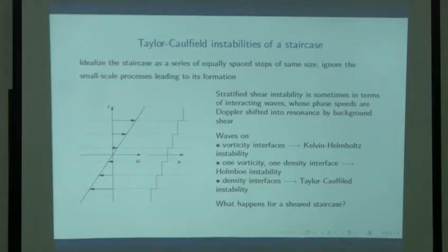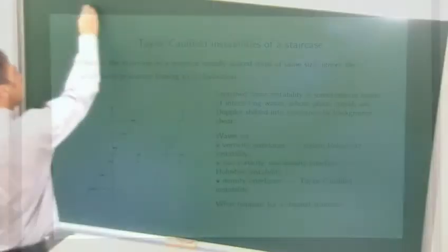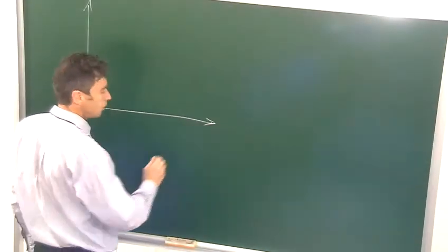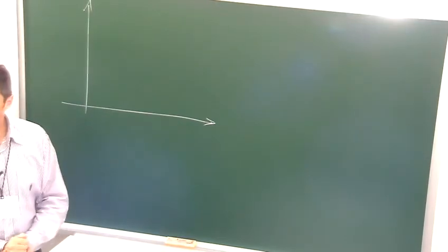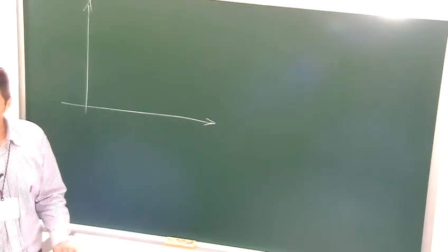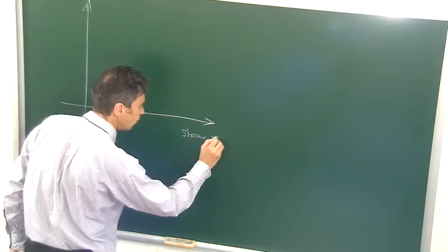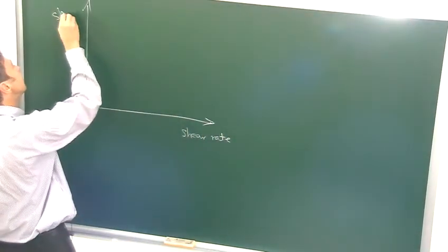So, rheometry. In rheometry, when you have a complicated fluid, you have something like two plates. You spin the top plate, or you have a plate and a cone. You put the fluid between these things. You measure, for example, the torque as a function of the rotation rate. And that allows you to build up a cartoon of the material behavior of non-Newtonian fluids. And the cartoon is usually portrayed as this picture where you have shear rate against shear stress.